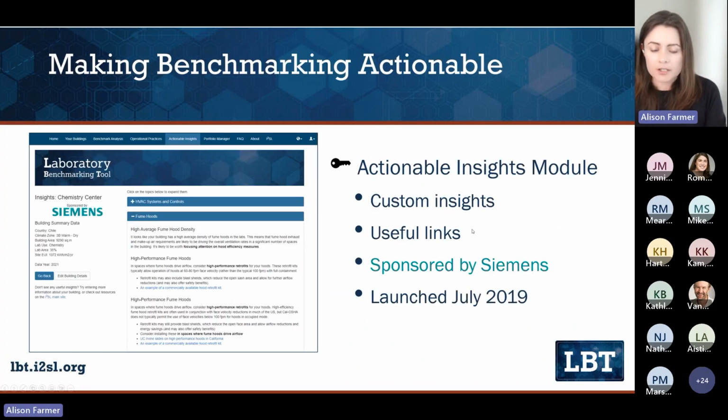The first one is the Actionable Insights module, and this is something that was sponsored by Siemens that we launched not long after the tool itself launched in 2019. What that module does is it takes non-energy data from the lab buildings that are entered, and it synthesizes that to make custom tips for energy efficiency measures for specific buildings. So for example, in this case, it's looking at this building and it's noticing that the building has a high density of fume hoods, and it's recommending that if you're looking for energy efficiency opportunities, it would be a good idea to look at the fume hoods and see whether you could implement some measures there. If on the other hand, the fume hood density had been lower, it would have advised you to look at overall room ventilation rates.